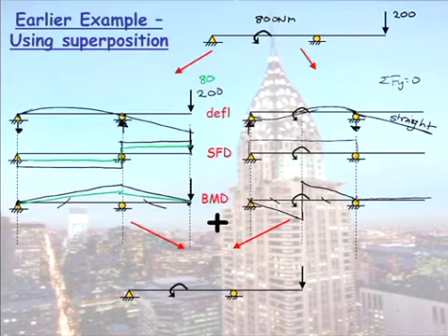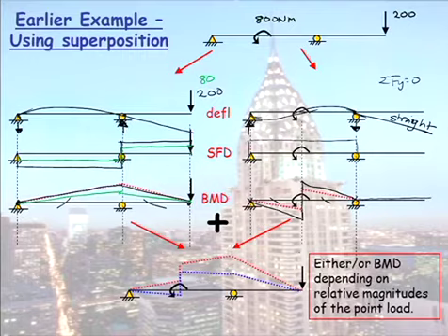So if I combine those two bending moment diagrams, can you see they combine in different ways? If that force here is 200, have a look. I have this, see this zigzag happening in here? So that zigzag action is a result of the bending moment caused by the applied moment. And this popping up here is a result of the point load.